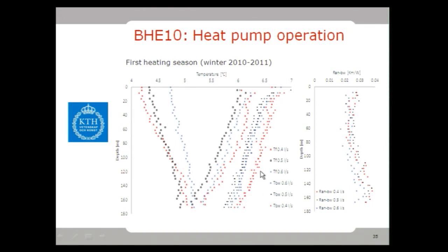With these measurements and the specific heat extraction rates, I calculated borehole resistances, or what I call annular to borehole wall resistances, which are, for the heat extraction cases, about 0.025 Kelvin meters per watt. It's compared to about 0.015, which were for the heating case.